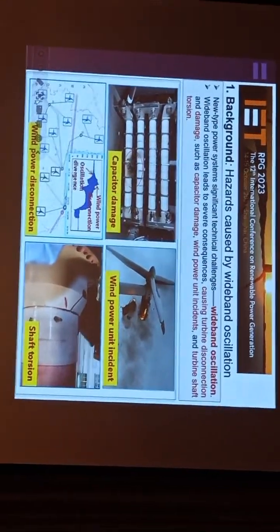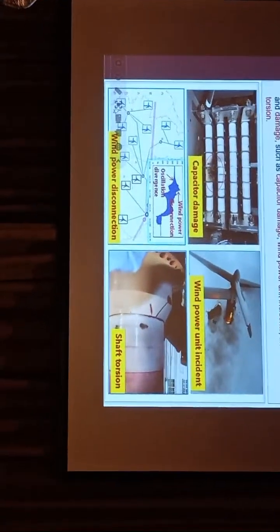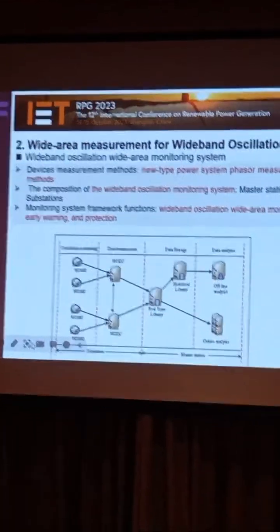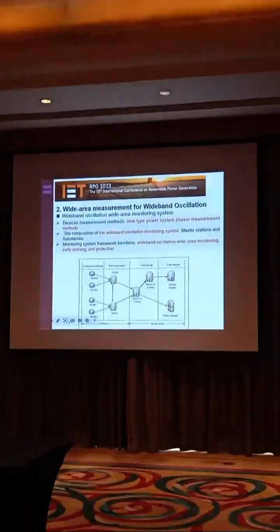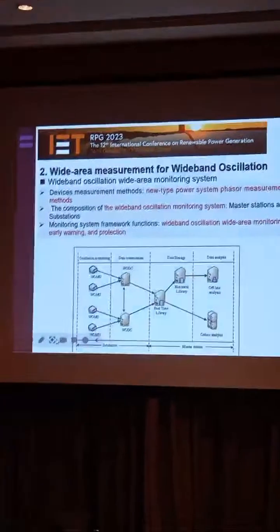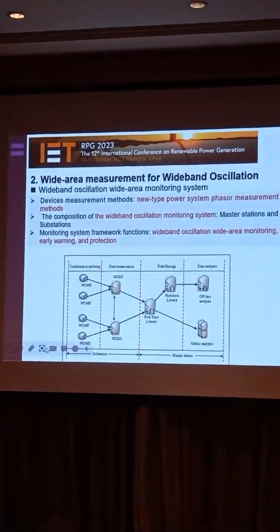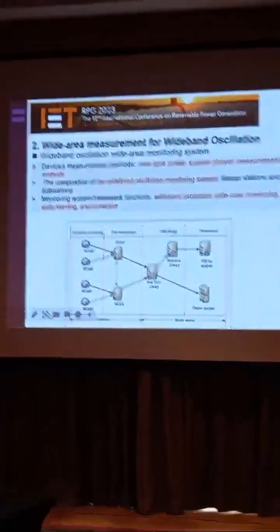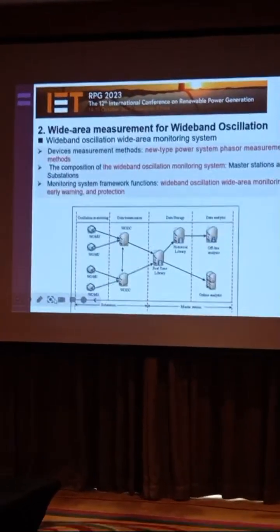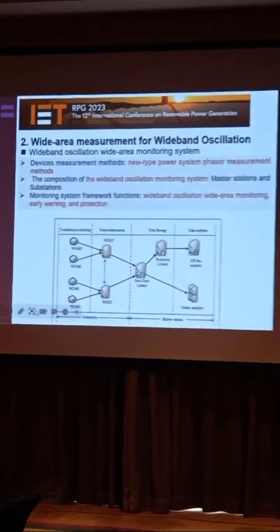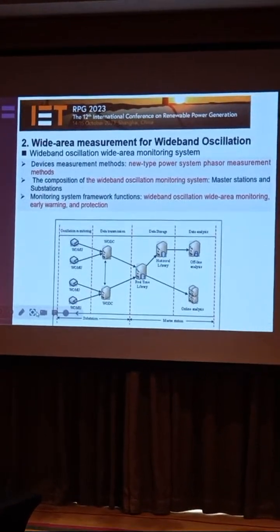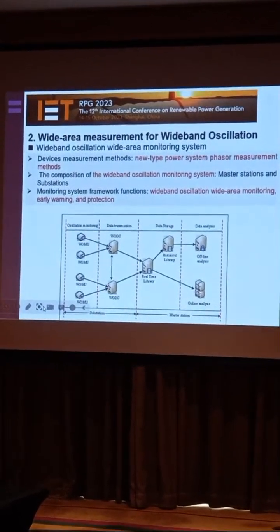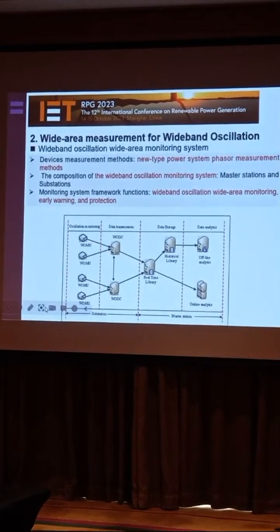Implement measures to avoid accidents and their spread. To detect wideband oscillations, we have designed a wideband monitoring system based on power system phasor measurement methods. The system comprises master stations and substations, enabling monitoring, early warning, and protection against wideband oscillations over a wide area.